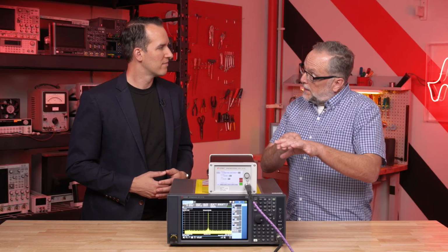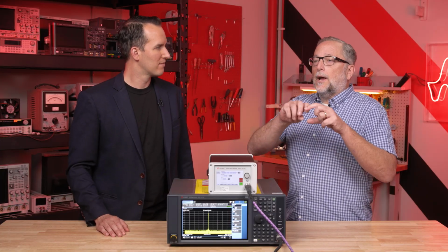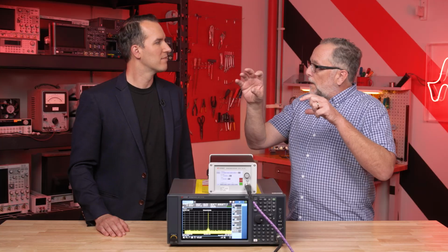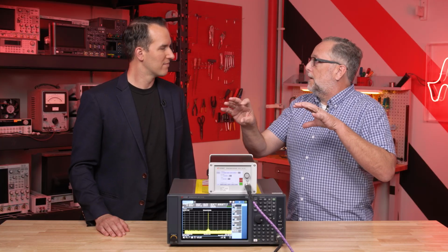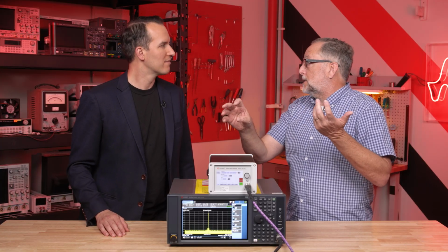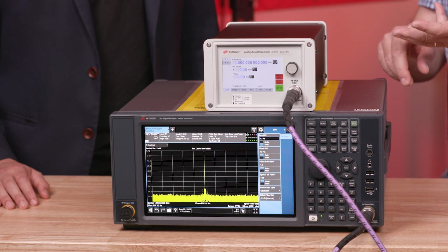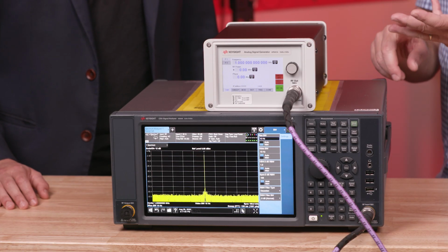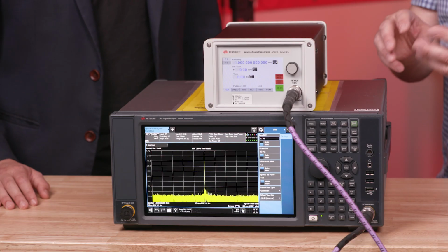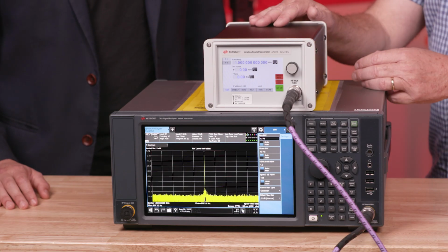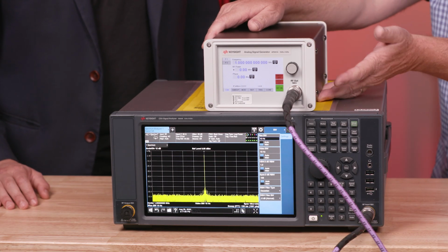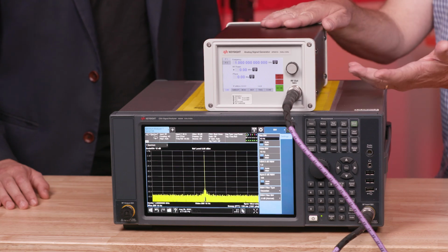And by having a very clean source as the LO, they're not going to have feedthrough of those distortion products into their converter and mess up their test, right? So with this, you've got a deterministic, very controllable, very clean analog generator to do that kind of work. But again, very low cost, very small. This thing weighs about 8 pounds and is very easy to lug around the lab.